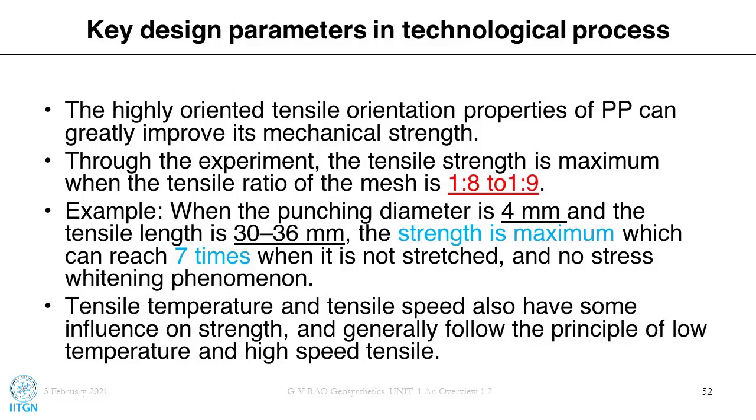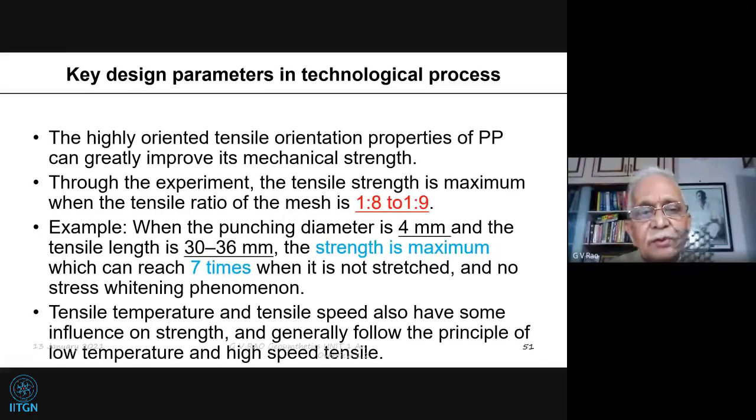So if you think of this kind of material, from your grid viewpoint, the strength is hardly 7 kilonewton per meter actually, whereas we're going to talk of grids and textiles of hundreds of kilonewtons or even 1,000 kilonewton per meter. So this is unoriented material. A net is unoriented, and of course, later we'll see that a grid is something oriented.